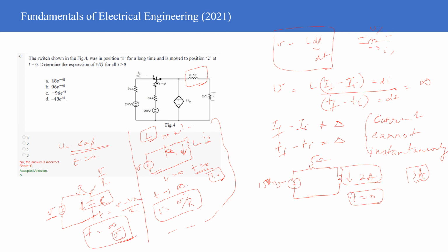And suppose there was no initial current in this inductor, then at time t equals 0, the inductor would have behaved as an open circuit, and the current which would have flowed in this circuit would have been equal to 0. So this is the conclusion which can be drawn from this particular expression which is written over here, right? This is a very important expression.